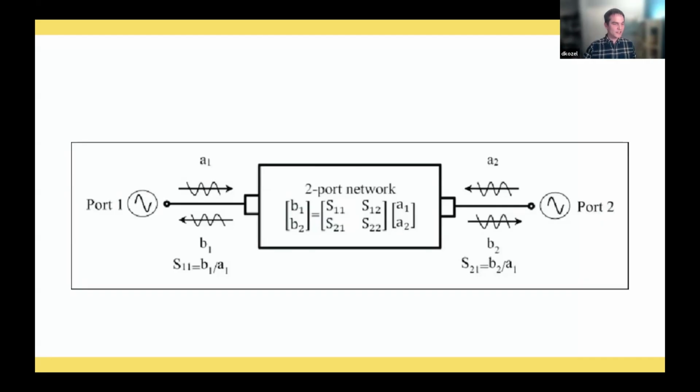So what quantities do we actually care about here? We care about our S parameters. These are our scattering parameters, and they're what you measure most of the time with a VNA. We'll see that SWR is kind of a different form of these values. S11, the S parameter from port 1 to port 1, is how you read that, is B1 over A1.